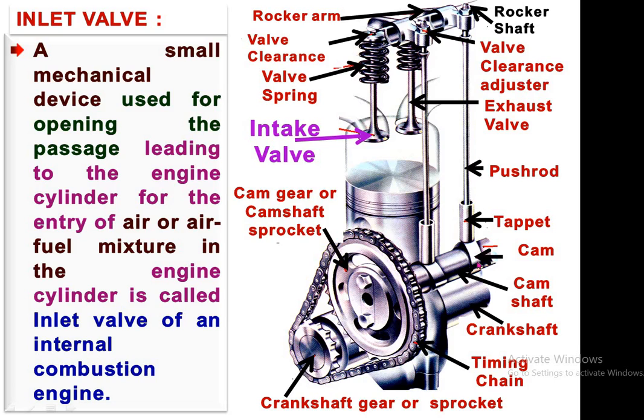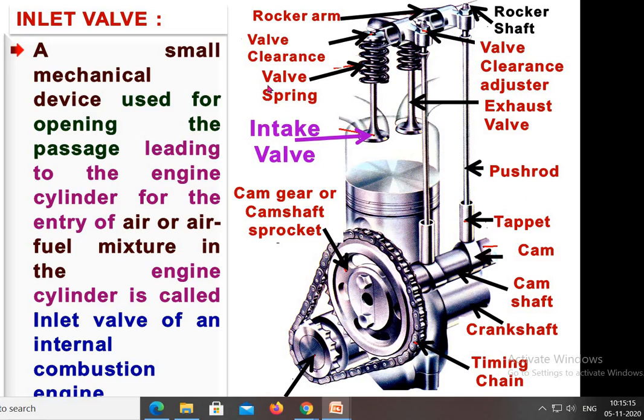As and when the cam gives upward movement to the tappet, through this upward movement the push rod pushes the rocker arm on the upside, due to which the other end of the rocker arm presses the valve inside. So this valve goes inside through this inlet valve. In the 4-stroke engine, fresh air comes in the clearance volume, or we can say inside the cylinder.